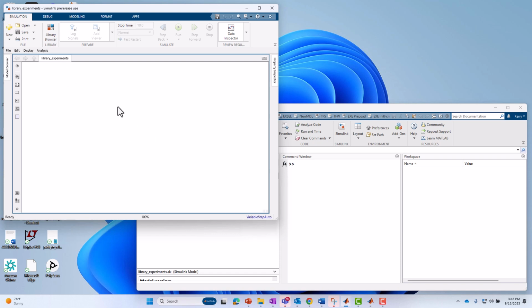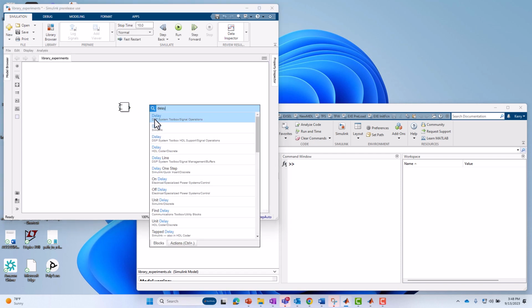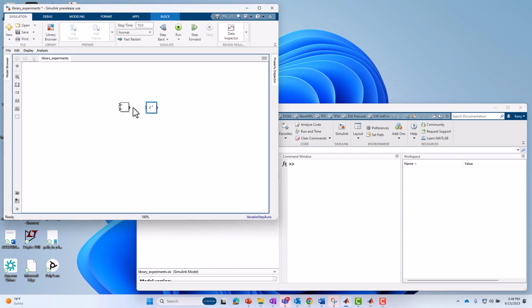All right, so the first thing I'm going to do is just create some very simple test design, and I'm going to start pulling in components like an adder, and I'm just typing in the workspace of my model to pull in names of components really quickly, start wiring them up. I'm going to pull in a gain block. Wire all these things up. And I'll put in another gain block as well. And I'm going to create a simple leaky integrator or low pass filter. We'll put that like that. We'll create a little feedback loop